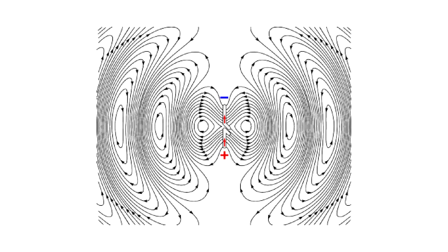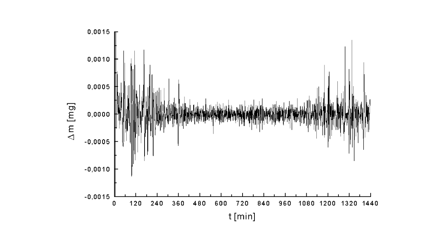Once they're generated, electromagnetic or radio waves travel through space directly or can have their path altered by reflection, refraction, diffraction. The intensity of the waves can be diminished because of dispersion, and likewise some of the energy might also be absorbed by various materials. Noise will also diminish the signal. This is called electromagnetic interference and comes from natural sources as well as artificial ones. If the magnitude of the noise is large enough, the signal won't be copyable anymore. The signal-to-noise ratio is a fundamental limit to the range of radio communications.